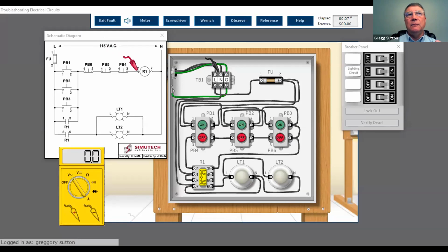So show me where that is down there. Go ahead and test in the control cabinet there. Okay, the relay schematic said it was terminal 2, so I gotta find that. It's right here. Okay, perfect. Now, what else do you have to do to get power there, though? Oh yeah, everything's open, so I gotta press a button. See if I get power.